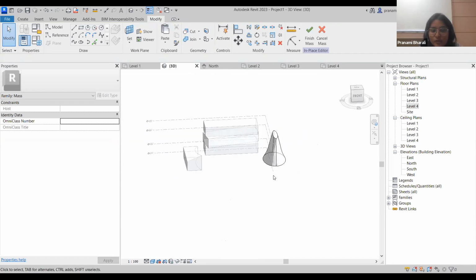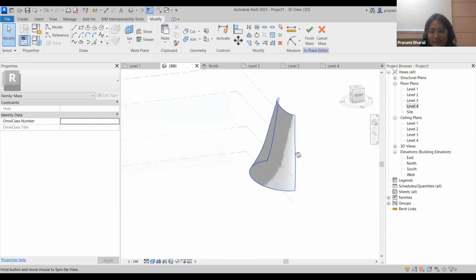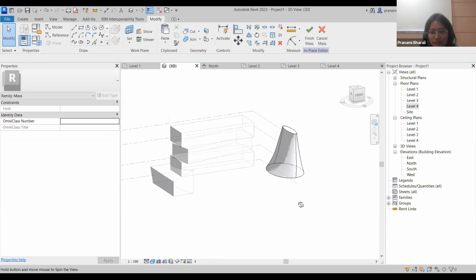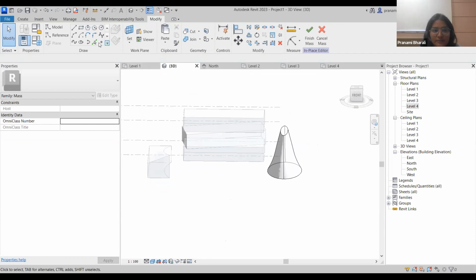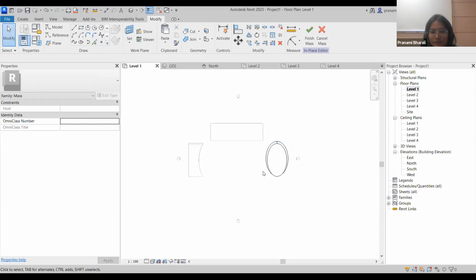Now next is that you want to make some kind of parametric group, suppose, right? So in that case, in the parametric roof, we have something called point element in here. Okay, so what is a point element now? This is what we created right now, whatever we created using line based. As you can see, we have this straight line or maybe different polygons and everything, but we have something called point element also. In the point element, what happens is that I'll just go to my level 1 here. In the point element, you can place points.